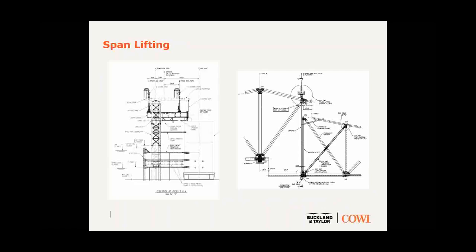But of course, we're lifting 2 spans over 3 piers. After we lift the first span, we no longer have the center pier available to us. And we had to move off 1 panel point. So since this would already be erected and we couldn't have a lifting point here, we moved off 1 panel point and put the lifting platform and strand jacks at the top of this panel point. So that became basically the highest work point in the project there, I think. And lifted, there's the strand jack assembly here lifted at that panel point. And here you can see the 2 splices that were made here and here once the second span was erected.